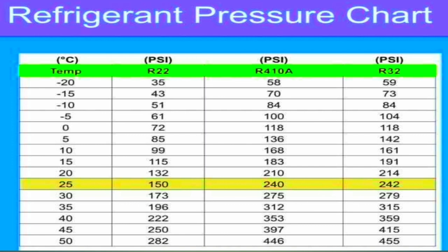Better you use these charts to fix your Freon properly, and if your Freon is properly charged in your unit, then the life of your compressor is longer. If your unit is overcharged with Freon, then it will damage your compressor also.